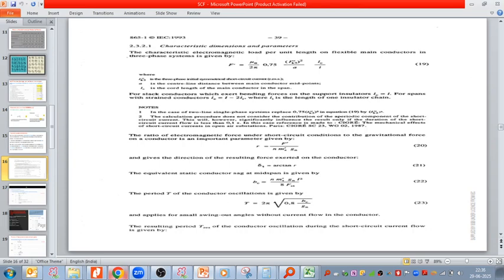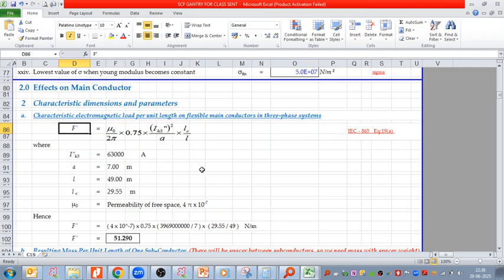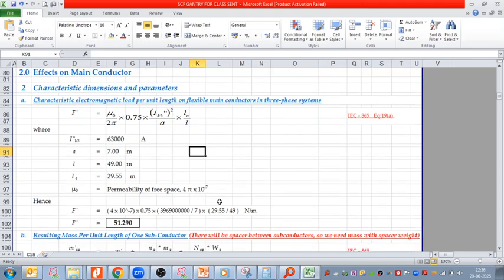No, sir, the premise of my question was whether for a three-phase fault, the equivalent force acting on the center of the supports, for all three, is equivalent to one force acting on the Y phase. Supposing RYB is there, then all of this force, with three phases shorting together, would be acting in a single direction on the Y phase, isn't it?